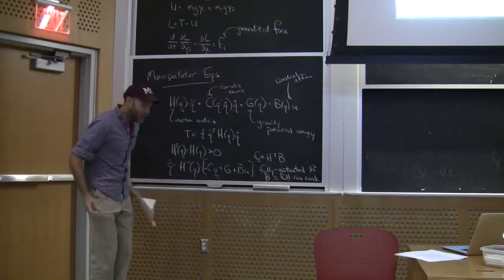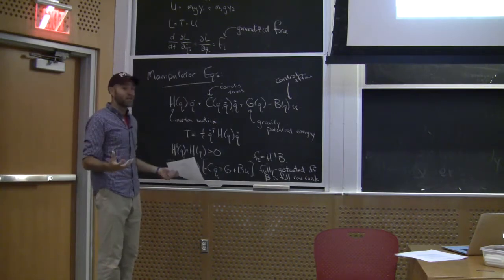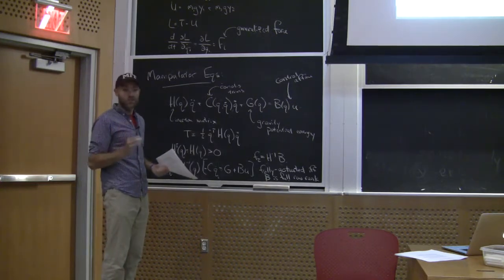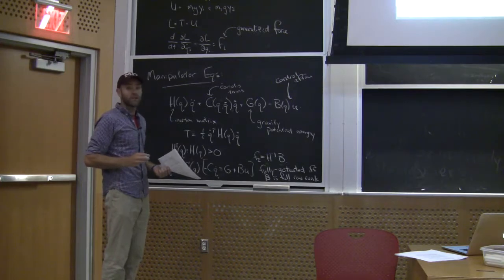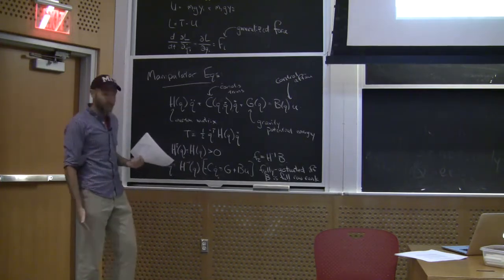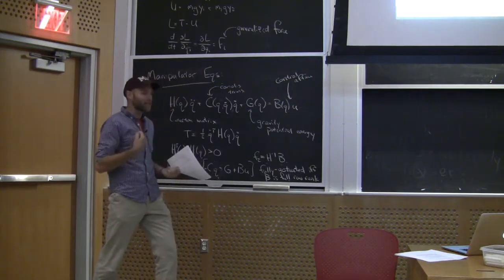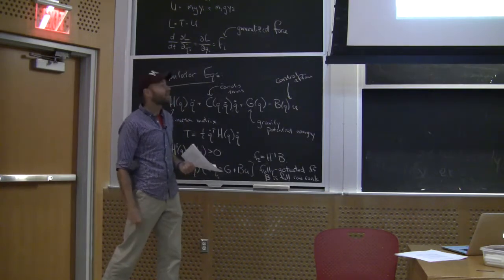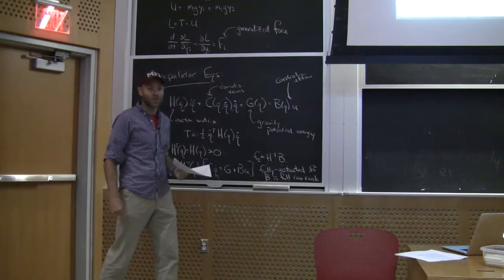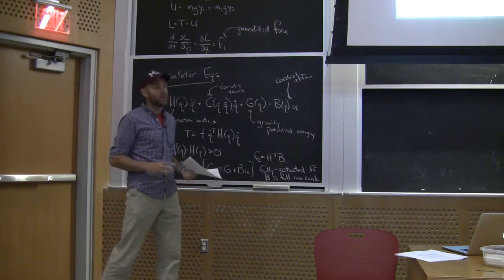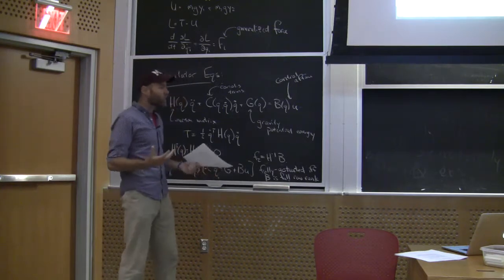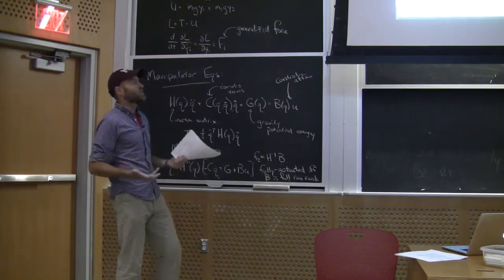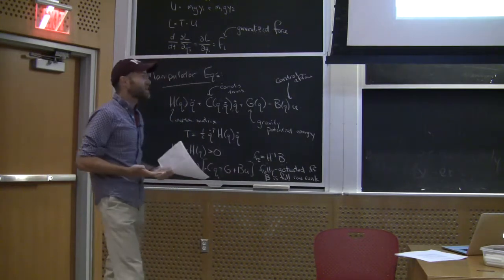But somehow, when I jump, let's neglect aerodynamics for a second, when I'm flying through the air, nothing I do with my muscles is going to change the trajectory of my center of mass. My system is underactuated, and it's because I'm not bolted to the ground. I've got this beautiful, complicated robot, and that last joint, the one that connects me to the ground, I don't have an actuator at my foot. That's just like not having an actuator at your shoulder here. And so a walking robot is underactuated. Airplanes, quadrotors, they're not attached to the ground. Quadrotors, if you have enough actuators, then you get some of the properties of having almost a fully actuated system back.